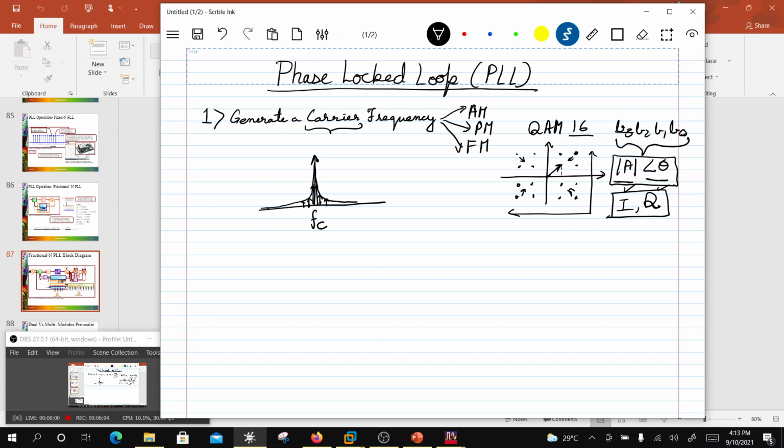Now what are these additional components going to do? If you have a single frequency, then you would receive any signal as is. But if there are other frequency components, they are also modulated, right? First, you are putting power into other spectrums, which is waste. Second, this will interfere with your demodulation, right? So the idea is the purer the tone, the better it is going to be, and this is done by a phase lock loop, right?